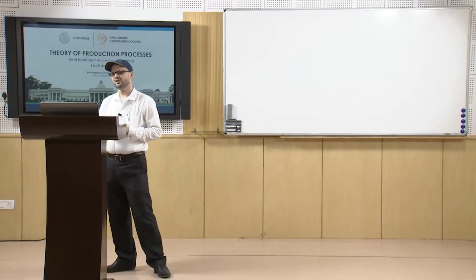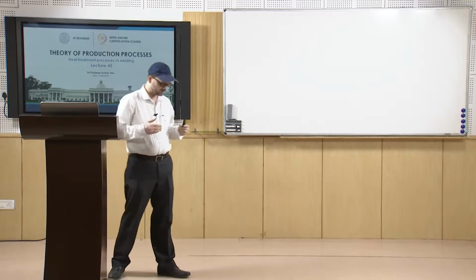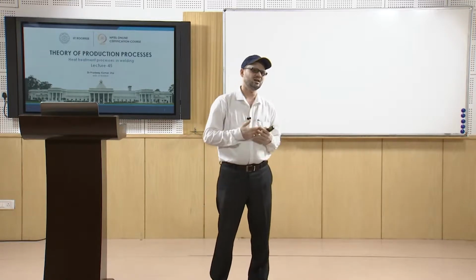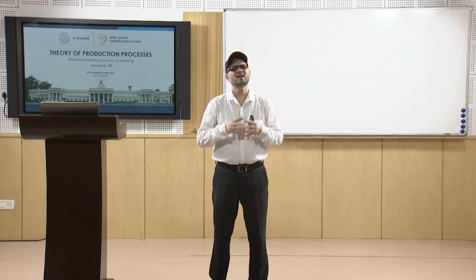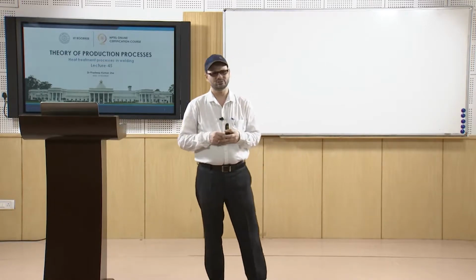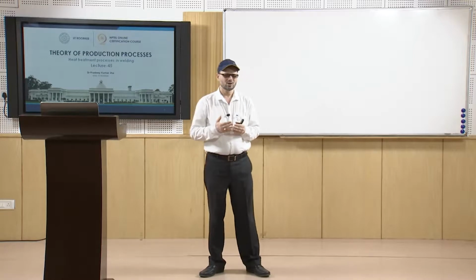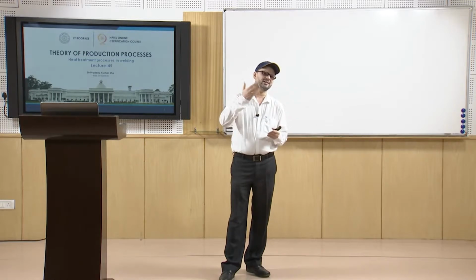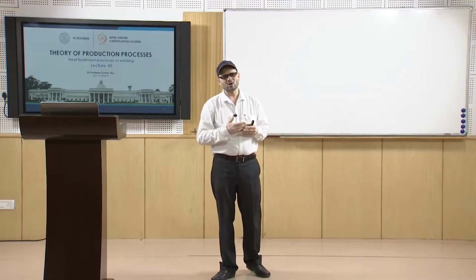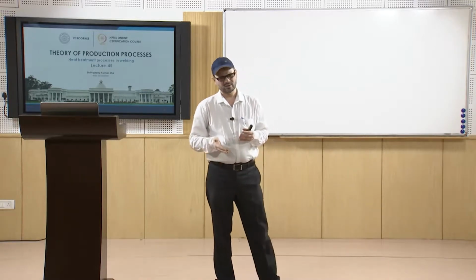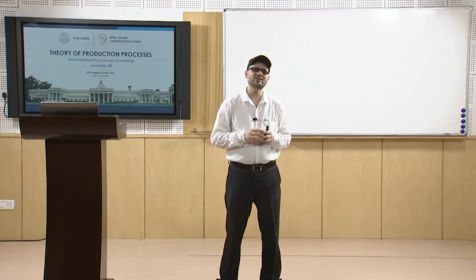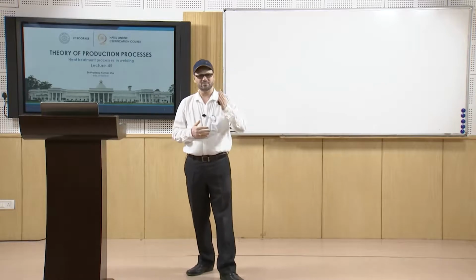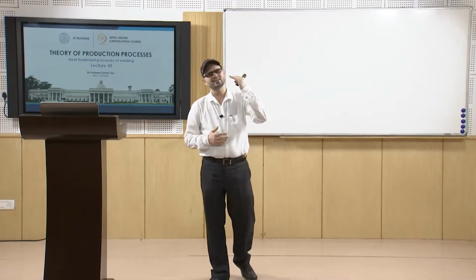Now, coming to the heat treatment processes in welding, we have discussed in the last class that there is a basic difference between the heat treatment process and the welding process. In welding also you have heating and then cooling. In heat treatment also we heat and then we cool. The only thing is how we heat, how we cool, and how long we retain it. So, there are three things in heat treatment: one is heating, one is retaining, another is cooling.